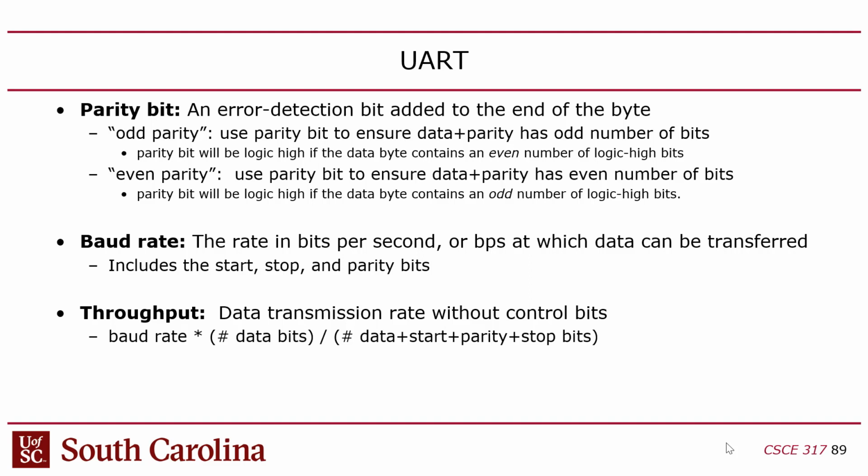Yes. Because it's an asynchronous protocol, and there's no clock rate negotiation in there, you can easily end up in a situation where you connect to some embedded device and you get back total gibberish, and you just have to try a bunch of different common baud rates until one of them starts spitting out ASCII characters on your terminal the way you expect. You have to guess if you don't know the parameters. Or you can look it up, but I never do that.